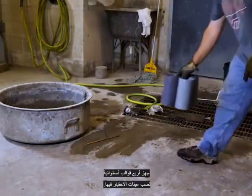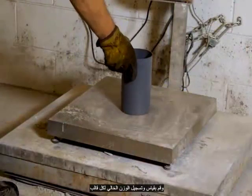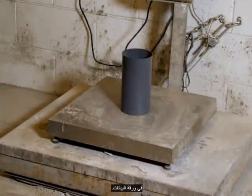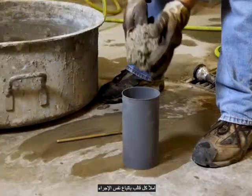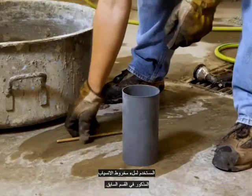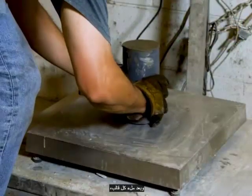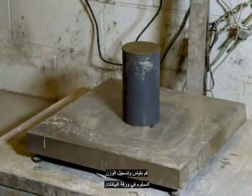Prepare 4 cylindrical molds for casting the test samples. Measure and record the empty weight of each mold on the datasheet. Fill each mold by following the same procedure used to fill the slump cone in the previous section. After filling each mold, measure and record the filled weight on the datasheet.